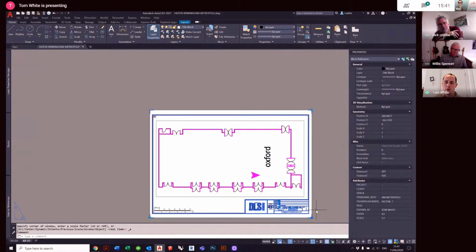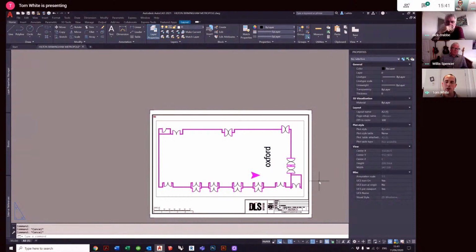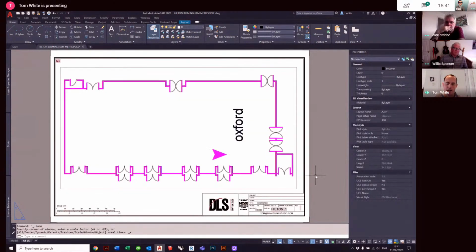But one positive, if at all possible, of importing it is because then you can change the X and Y. Because I could be speaking out of turn, but I'm fairly certain that when it's a PDF underlay, you can't change the X and Y scale ratio. They always have to match, so they all have to be 1-to-1 or 0.9 to 0.9. I believe that when it's a PDF underlay, you can't do that. And when you have a scenario where we know one measurement and we know the second measurement, but they don't match, I don't believe there's a way of scaling.